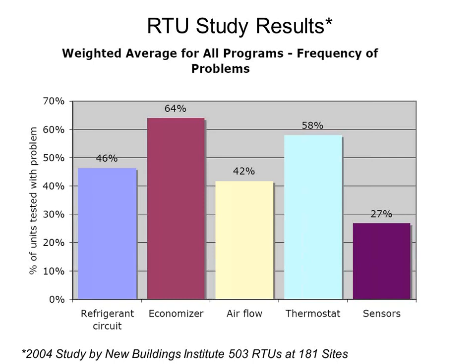So 64% of the time, the economizer was not working. For you guys that are math whizzes, that's more than half of the time, right? And not working usually meant that it was broken, but it could have also been that it had just really screwed up settings that allowed it to barely operate. So problems that were incurred would be things like somebody propped open the damper with a 2x4. I know that's shocking to most of you, but people do that frequently. Somebody screwed the economizer damper shut so it would never open again. That also happens fairly frequently. The actuator is not on the damper shaft. It's laying on the ground. Why is it not on the shaft, right? And then to the less dramatic things like my economizer set point is not the optimal set point. Somebody set it to only change over at 45 degrees, instead of something more conservative that we'll talk about in a minute. So that was the most common.